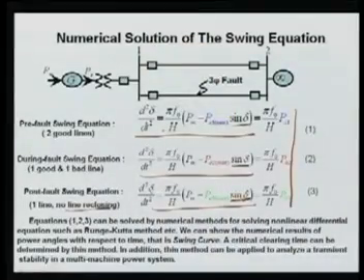Moreover, this swing equation we have modeled with a simple classical approach, and that is not always valid. We have to go for detailed modeling of the machine. Here we have made 7 assumptions that can be relaxed, and then there will be several hundreds of machines in a big power system. All these will be solved for the system. Then we can see the performance, the delta variation of each individual generator.